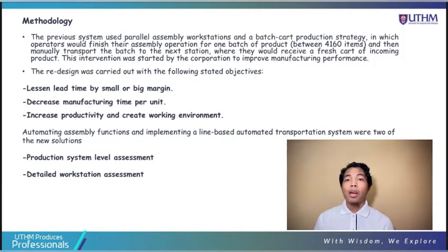In this assessment, a two-dimensional static link segment model was utilized to determine the shoulder moment for each activity in the manual assembly. The video analysis was utilized to identify the duration of operations, which was then utilized to calculate the weighted average shoulder moment and cumulative load per product.